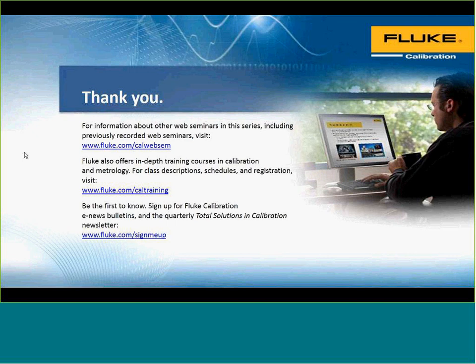The 6270 has multiple ranges with negative gauge that can handle vacuum. We don't have a vacuum module sensor that you just plug in, but there are some absolute sensors available, such as the low absolute A100K full scale, that will do atmospheric pressures in absolute mode.